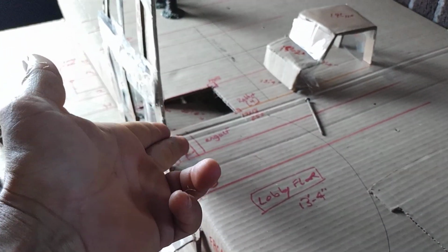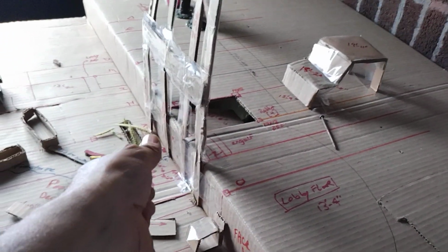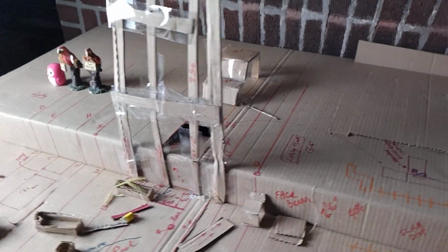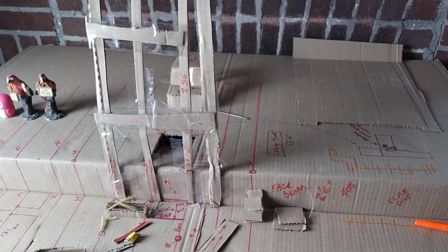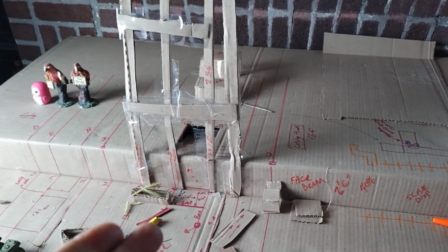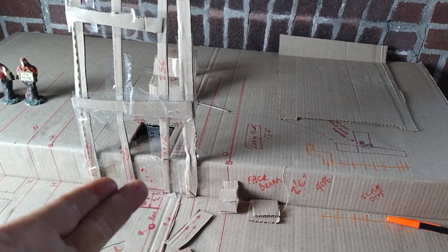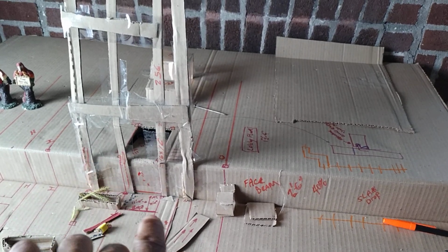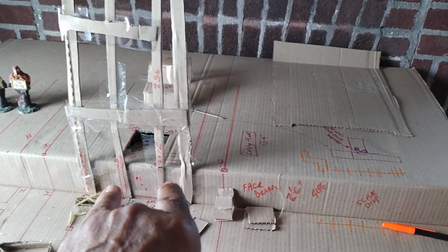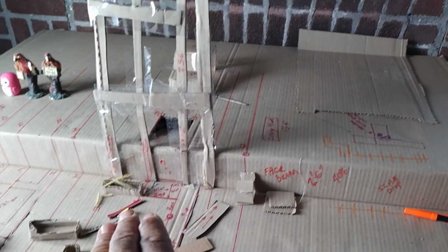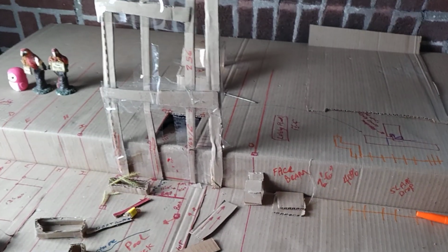It drops. Boom. It's not for free. It wants to pull on this now. It does pull on it. And then we get that 7-minute delay time. I'm showing you that 7 minutes can happen where you have a stress there and nothing. But possibly, this is only 1'6", possibly it tore out more of this than we think, but more so under, possibly, maybe equally even under both of these, under M and N. I doubt it because the reinforcement's different at that location on each one of these columns. I'll show that in future videos.